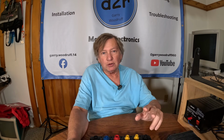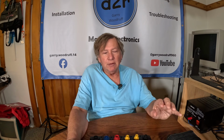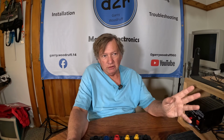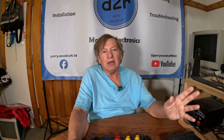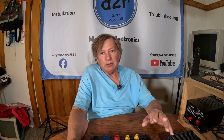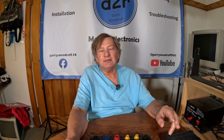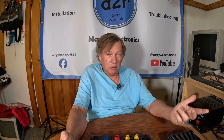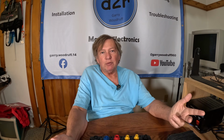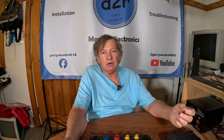So say you had one of them turned on, maybe one on standby. I'm not sure if they transmit on standby. But if you had one on, one powered off, and then the other one's your console, the one you're working with, say the console at the bow, you punch the waypoint, one unit wouldn't pick it up, the other would pick it up. Now you possibly have two different sets of waypoints in your machines. One unit would have all the waypoints but the new one. The other one would have all the waypoints including the new one. But the numbering system may have gotten off. And that was one problem I always had.